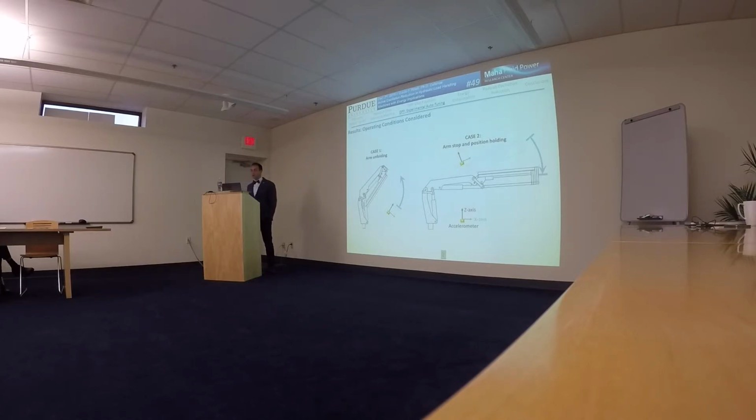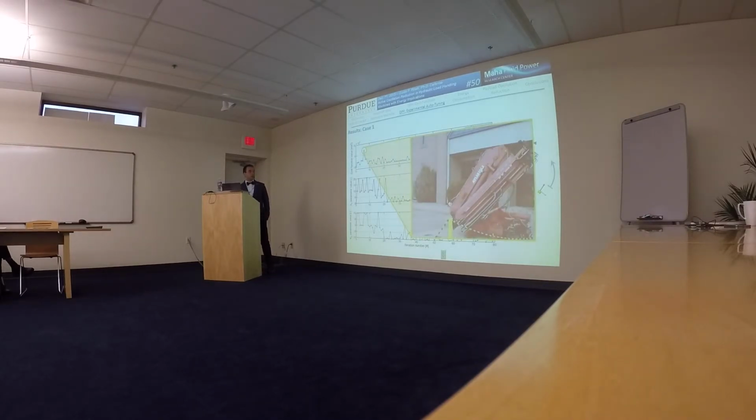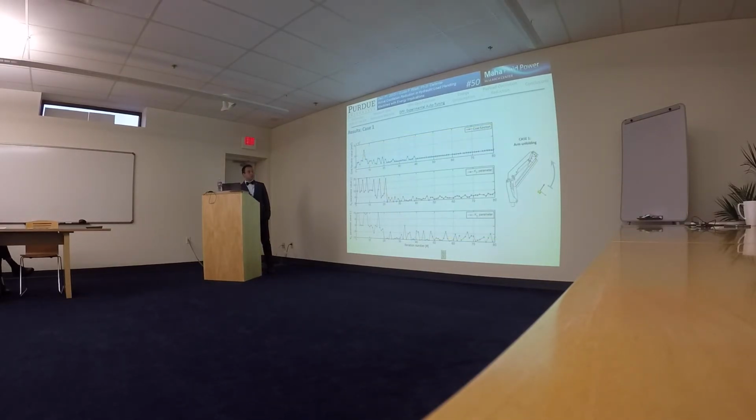so the main boom unfolding and the stop of the main boom after the folding. And so for the first operating condition, here we can see the result of the optimization, where we have the cost function and the two parameters for the controller. And as you can see, after about 50 iterations, we reach the convergence or the minimization of the cost function. So now, by using a small amount of iterations, we can actually see the minimization of this cost function.